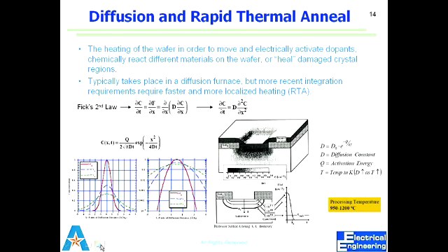So this is that idea that we start with a certain depth, but with time this would increase to take more depth. So this is 10 to the 21, 10 to the 19, 10 to the 16, and then essentially when it drops off, it goes to the background concentration, which is 10 raised to 10. So again, these are two cases of limited and unlimited supply. So this is unlimited, this is limited.